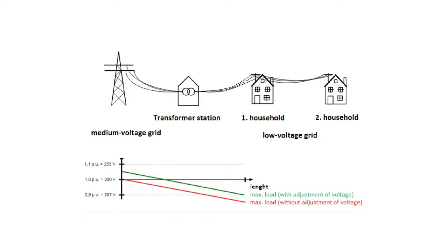In the real case, and without private photovoltaic systems, the voltage is at the transformer's highest and falls even further due to line resistance with increasing distance from the transformer. In the end, all households have a different voltage applied. In Germany, the nominal value of the voltage has been defined as 230 volts and may vary for a secure supply to a maximum of only 10% of this value. With the installation of private photovoltaic systems, it may cause overvoltage.